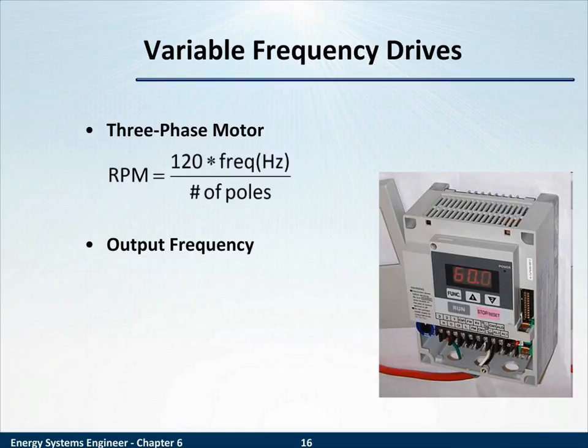The first equation at the top of this page: RPM equals 120 times the frequency divided by the number of poles. Earlier, I said RPM was 7,200 divided by the number of poles. Well, that's strictly speaking for 60 Hertz AC. When you consider the terms variable speed drive, variable frequency drive, the speed is the rotational speed. So you see from this first equation as well that a variable speed drive, variable frequency drive involves the same manipulation of speed and frequency.